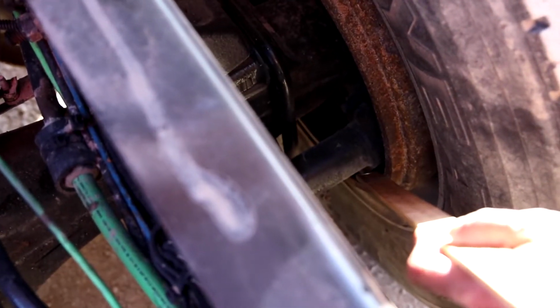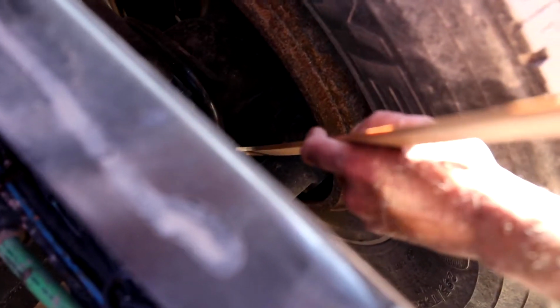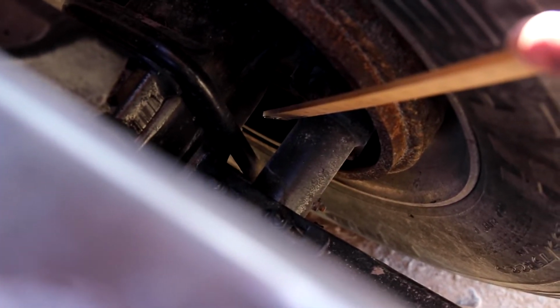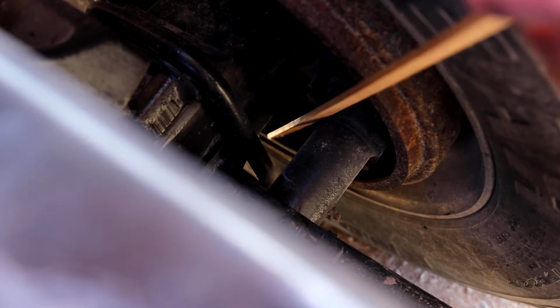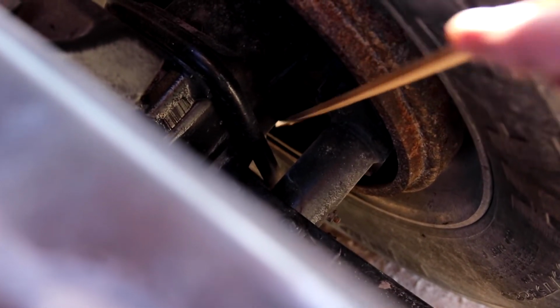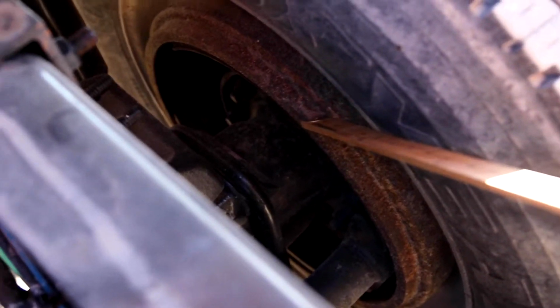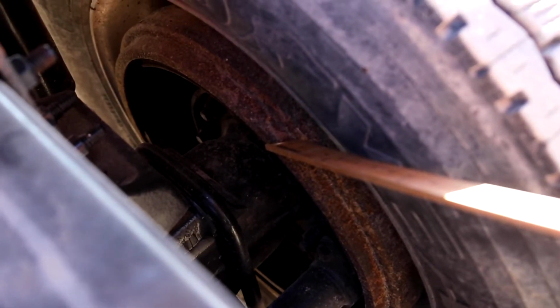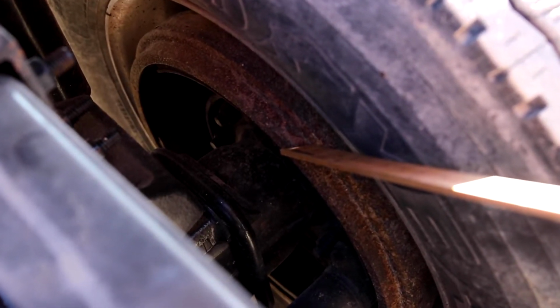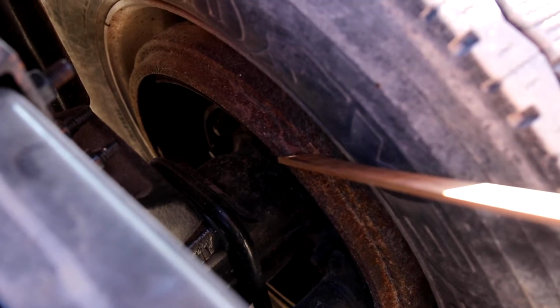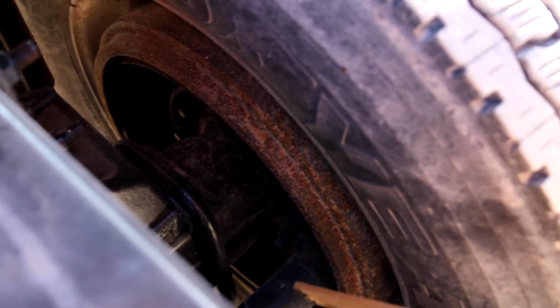So again, we're going to go to our brakes. And again, look at your brake shoes and linings here at the top and bottom. No debris, no oil or grease. And again, they must have at least 1/4 inch of thickness on the brake shoes themselves. Then you have the brake drum again, right in through here. It is not damaged or broken. No cracks, no illegal welds. No oil or grease on them. Then we're going to move on to our suspension.